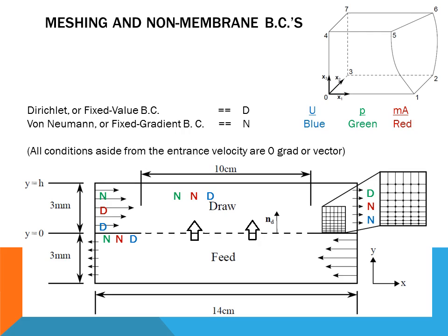Okay, so these are the basic boundary conditions. Nothing really special on the walls. It's just zero gradient, zero velocity. The velocity profile here is parabolic and actually uses the SWAK4Foam that was mentioned earlier. Pretty simple implementation. The membrane has the special boundary conditions. It has an optional slip velocity, which I'll show you later, and a special gradient for mass fraction. The pressure is a zero gradient, just like all the walls.